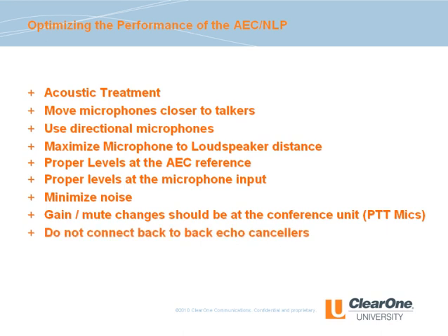Do not connect back-to-back echo cancellers. This can occur when using video conferencing systems with echo cancellation. You should disable the echo canceller in the video codec. Doing the opposite effectively turns your system into a single-channel echo canceller and is not recommended. Anything you can do to improve acoustic echo canceller performance will result in improved audio quality and intelligibility.